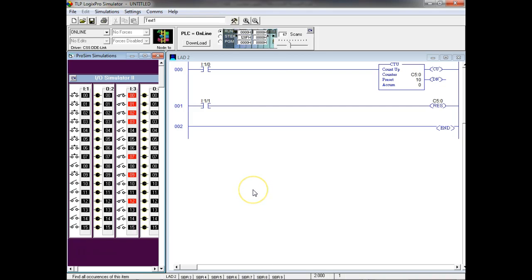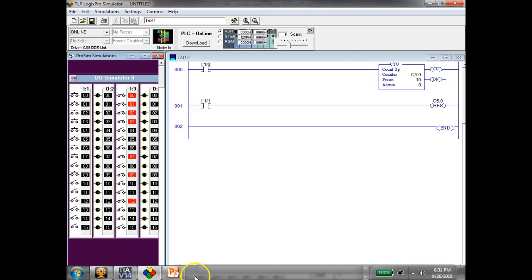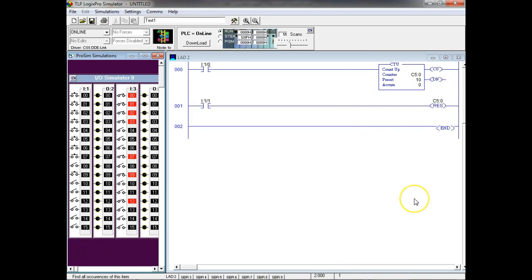Okay. So everybody okay on up counters? Pretty straightforward. Not much to them, right? And you can see why industry likes to keep up with stuff that they do, right? So you'll run into counters. By the way, in advanced PLC, the problem we have with these counters is these are software. Every time you insert one of these instructions inside your program, there's a little subroutine put inside your machine code program that handles counters. And it's software, guys. The biggest problem we have with software is that it never can be as fast as hardware. But the nice thing about software is you can change it.